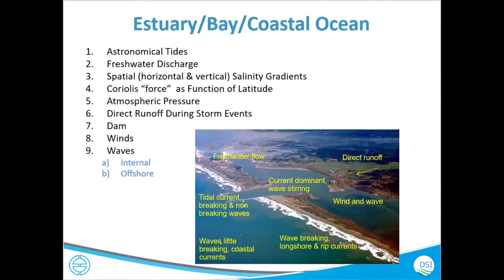This is similar to the previous one. Here you can have waves, and then you can have breaking waves, you have surge. So it's important to have a wave component in these kinds of situations. Sometimes there will be high tides, so you might want to extend your bathymetric grids in these kinds of regions, so you can represent whether those cells are wet during the high waves or not. The direct flows, there will be smaller tributaries.